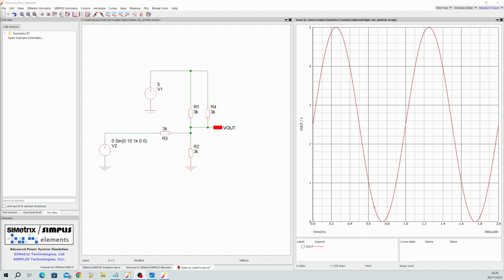It's quite key, this is. So put them all on top layer or all on bottom layer, but make sure they're all together in the same area as close as possible.